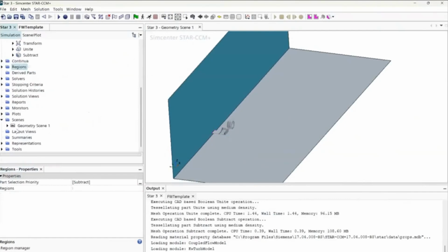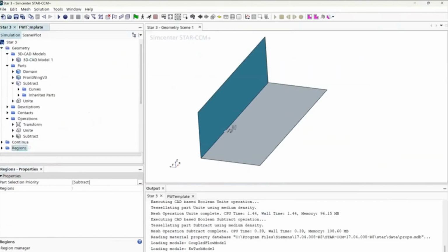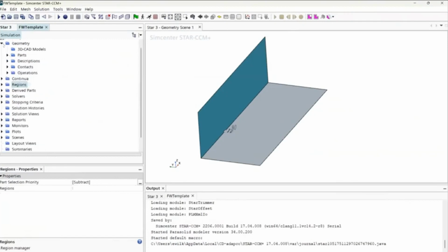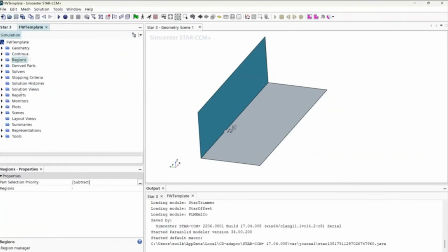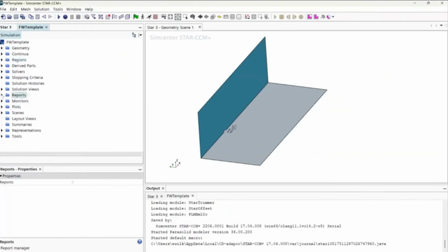The last thing really to do is set up mesh, and then we can run. Of course, there's also post-processing. It's honestly just copying, because it's a lot of repetitive datum plane, section planes. But right now we want to do mesh. Now, the thing about mesh is we want it to be consistent. If we change the mesh, make it finer or less fine, with the same geometry, you'll get different values for your reports. It is very important that you keep the mesh consistent. So which is why I'm just going to copy over the mesh.